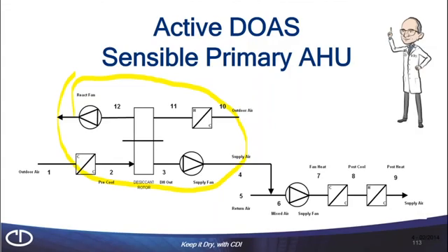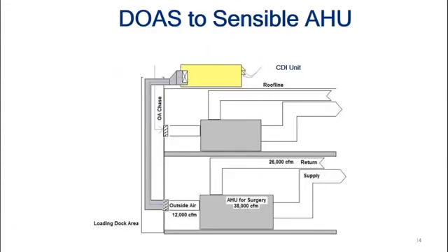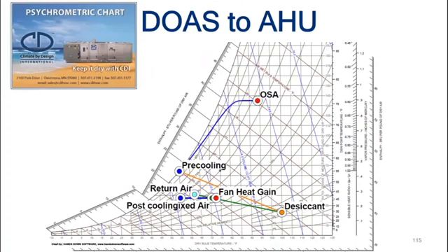We take the outside air, the 4 air changes, and pre-cool it to get most of the moisture off, or some kind of a first stage device. Then go through the active desiccant. We provide air that is, if you will, over-dried, so that when it mixes with the return air, now we're going through the rest of the system. This cooling coil that's in the system now is sensible only. And we're discharging air that's below your 60% relative humidity. That includes then the ductwork. So now the ductwork is going to be dry as well.